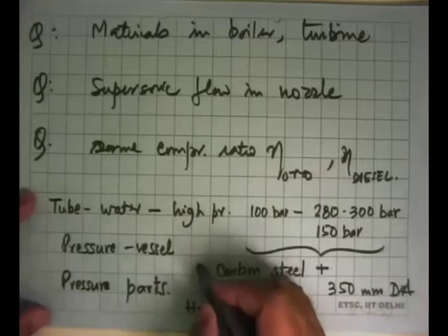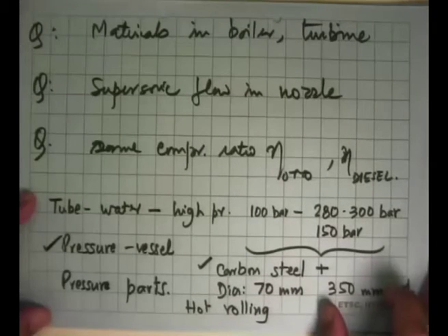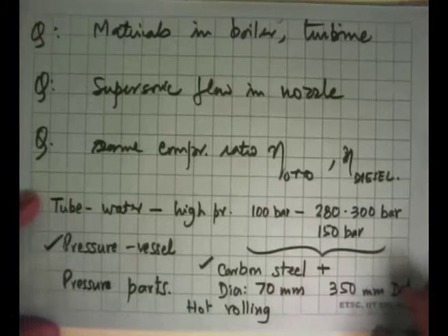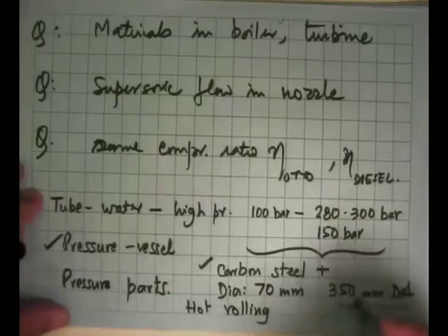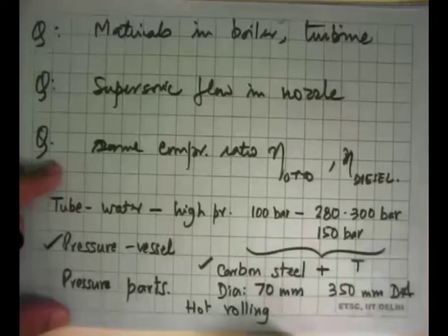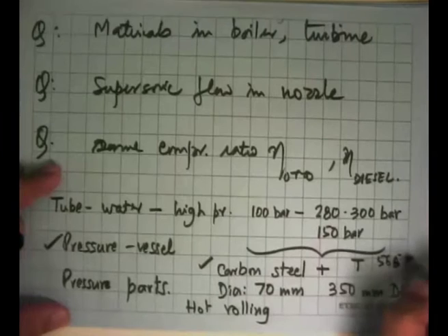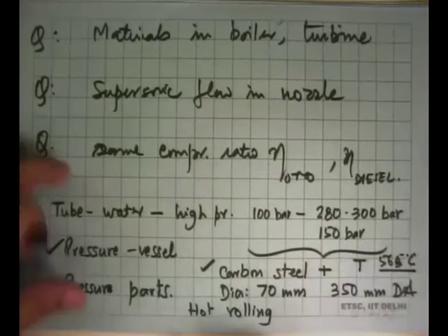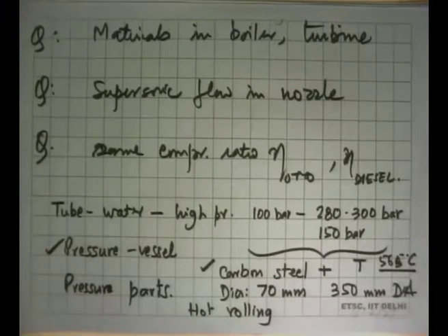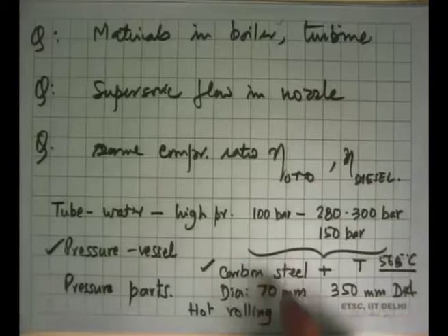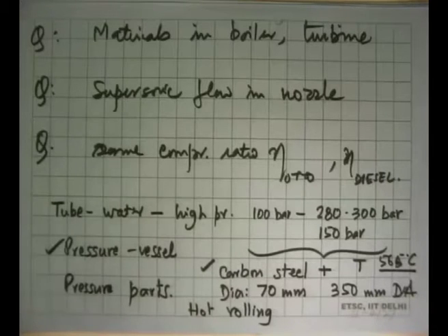Most of the tubes and pressure parts are of carbon steel. And how we selected these is that we needed to go to the temperatures that our cycles are telling us, like 560, 600 degrees Celsius, that type of temperatures. And our objective is that they should have strength and integrity at that elevated temperature continuously, year after year, for maybe 20, 30 years. That is the whole thing. So that's what's done in boiler tubes.